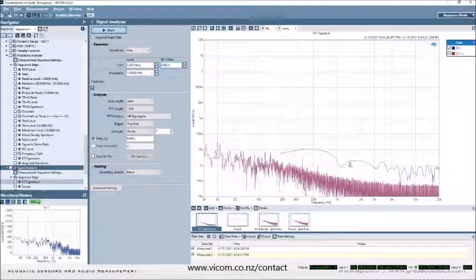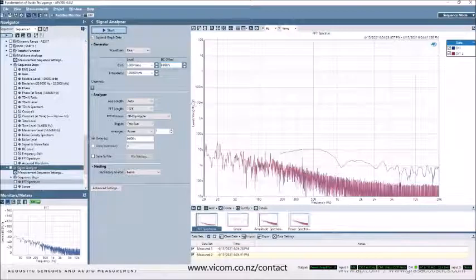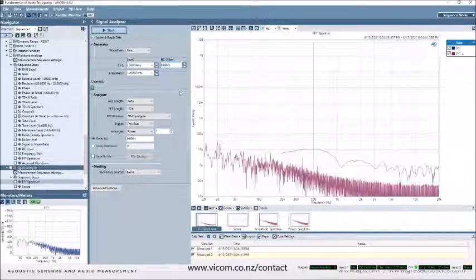So here I did a really short FFT, and below it I did a much longer FFT, and you might say, well, did the noise go down? So this is an RMS scaled FFT, and the key is this. If I am measuring a coherent signal like a sine wave, they will both return the same amplitude. But if I'm measuring noise, the longer the RMS scaled FFT, the lower the amplitude of the noise will appear to be.